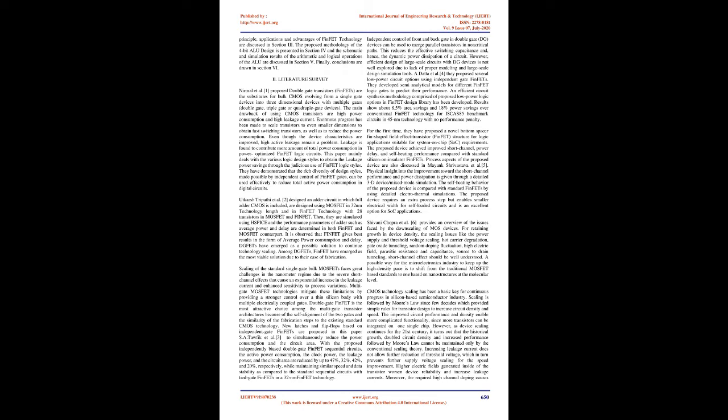To overcome these issues, a new device methodology for the processing element design is proposed using FinFET technology. The advantages of FinFET technology are higher drain current and switching speed, less than half the dynamic power requirement, and less static leakage current. The static CMOS logic is the previously known popular robust one, but it has a major drawback of leakage current and slow performance. Dynamic logic style is the high-performance circuit with low power dissipation, but that compromises its robustness. In sub-threshold logic, the circuit works with a supply VDD which is lower than the threshold of the transistor. In the saturation region, CMOS logic consumes more power as compared to the same logic operating in the sub-threshold region. In order to cut down dynamic power expenditure, the adiabatic logic can be used, which has strong inversion without affecting noise immunity.